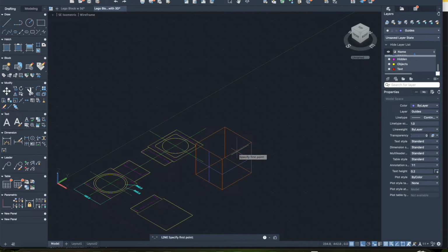Remember, if you don't see that triangle, you have to turn it on under OSNAP. Okay. And at the top, if you look at the top view, there's an indent area there between the very edge and the box that surrounds the circle, and it's 10 units. So what we'll do is we'll create another guideline here. It just extends in 10 and hit spacebar.